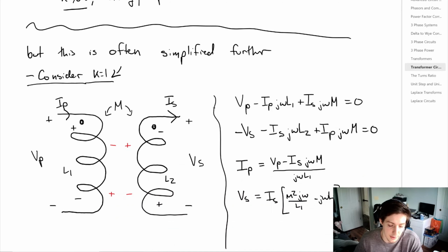We're just going to look at the primary and the secondary windings. So we're going to have current going into a dot, which means we are going to have a positive reference at the other dot here in red. And we know that this current that's leaving the dot can also be expressed as current going into an undotted terminal, which will have a positive voltage reference at the other side of the undotted terminal. So we get polarities that look like this for the coupling.